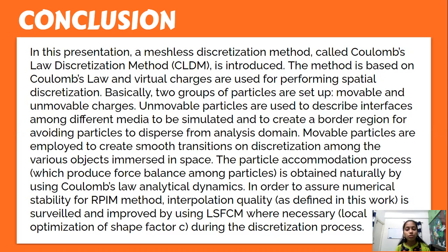Unmovable particles are used to describe interfaces among different media and to create a border region for avoiding particles dispersing from the analysis domain. Movable particles are employed to create smooth transitions in discretization among the various objects immersed in space. The particle accommodation process, which produces force balance among the particles, is obtained naturally by using Coulomb's law analytic dynamics.